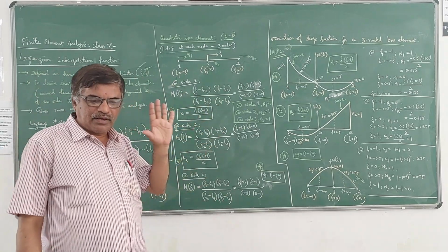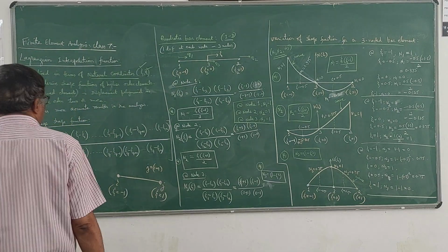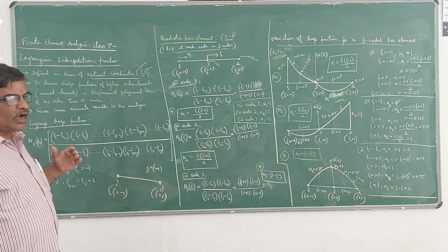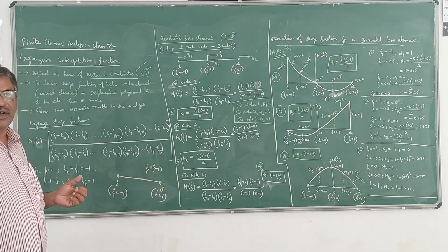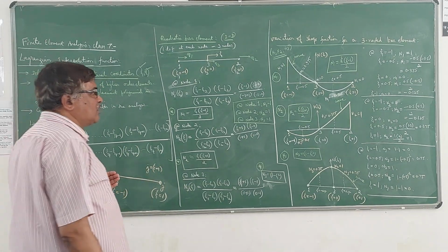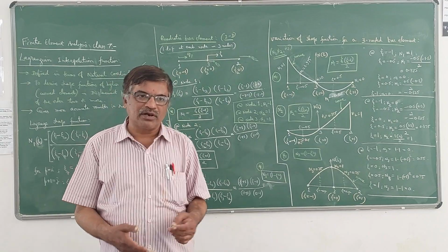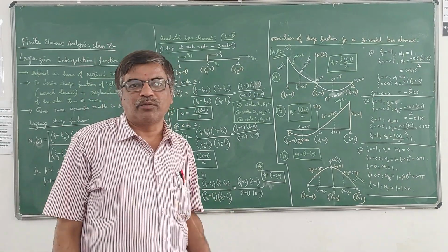This is the procedure of how to use Lagrangian interpolation to get the shape functions of higher order elements. It is a very useful concept in finite element analysis. In terms of natural coordinates, we can always derive the shape functions of one-dimensional, two-dimensional or even three-dimensional elements using Lagrangian interpolation functions.